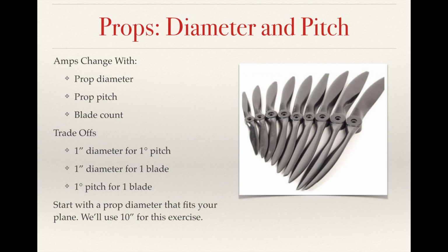So let's say that you're flying a 3-blade, but you want the plane to go faster. So let's say you've got a 10-5 3-blade prop. You could go to a 10-6 2-blade prop. So you give up a blade, but you increase your pitch.